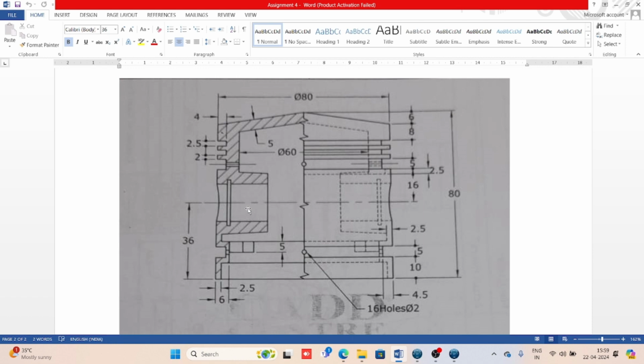If it is a process of milling operation or turning operation, in that case we can't proceed like this the way we are proceeding right now, because in this first we are removing this material and then we are adding this material practically, which is not possible. But though it is a casting job, so the step process will not be required in the CAD model, so we can proceed anyway, the way we are comfortable with the CAD tools. Clear? So now we have created this.